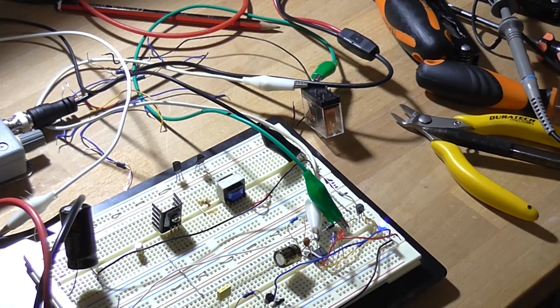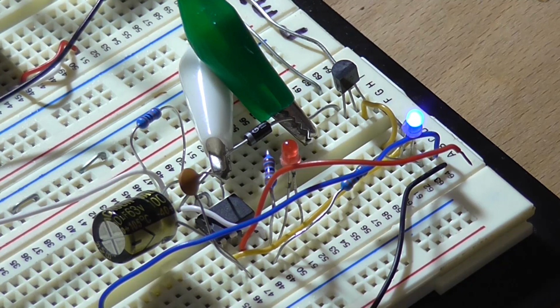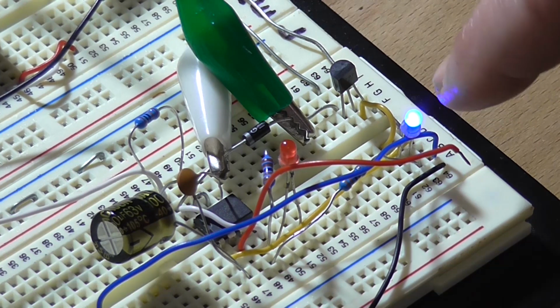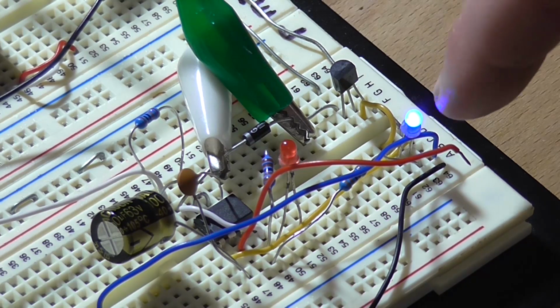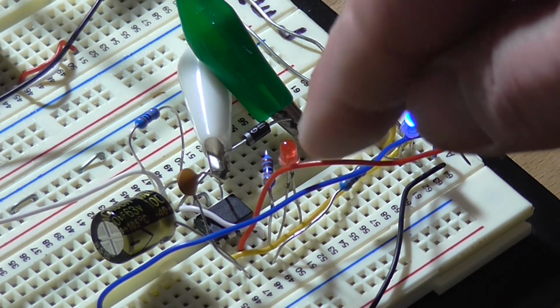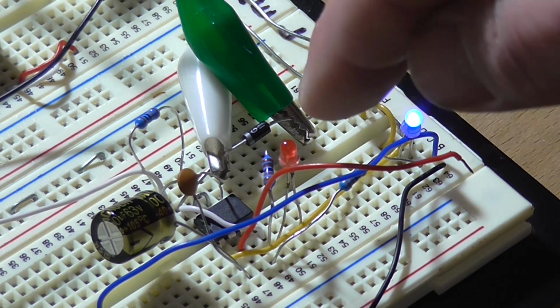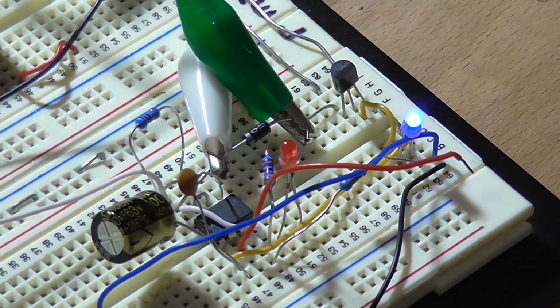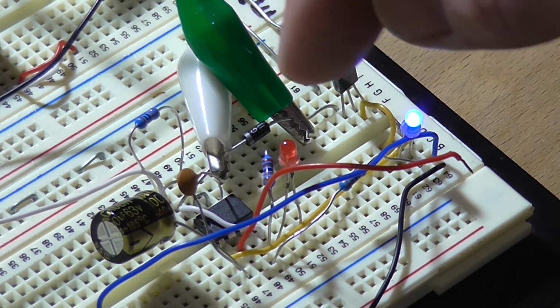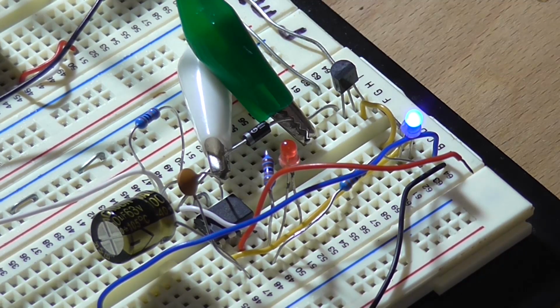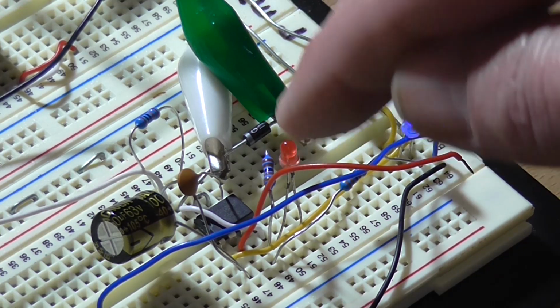Well, that's kind of unfortunate. The output state is high. I've got an LED connected in series with the base of this transistor, just to give me an indication of when it's in the high state. There's also another LED here, a red one, which indicates when it's in the low state. The cathode goes to pin 3, through a resistor to ground. And there is a slight little bit of a pulse here.